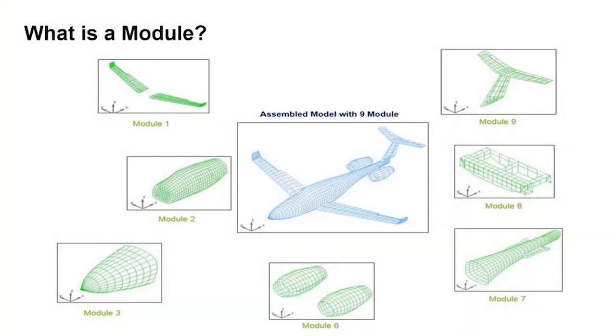So next I'm going to be talking about modules. So what is a module? This is a useful feature that has been added, and it has multiple applications in several industries such as auto and aero. So today's industry requirements call for design of complex structures, as I said, again, a similar concept, that have multiple components, parts, and assemblies, and combining these parts and assemblies can be tedious and cumbersome at cases. So modules are similar to part super elements, however, they don't have any reduction, so that's the benefit. It gives you more capabilities, so you have more control using the module.